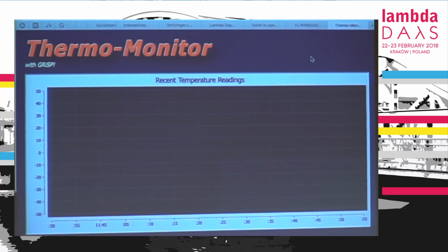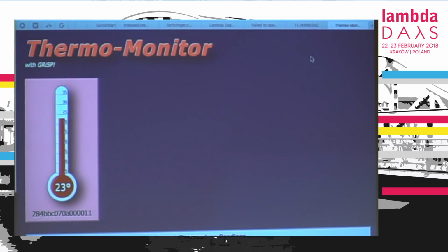The scan is running every 10, 15 seconds. The reason it's not snappier is that one-wire is actually a really slow protocol, and for this demo we're kind of abusing it. We're running these things much faster than you normally would if you wired this up in your home, just so we can see some nice things on screen. Normally you would never run the scan regularly. You would maybe have an interface where, if you plugged a new sensor in a new room, you would go and do it manually. For this demo, we automated it, so it looks a bit more fancy.